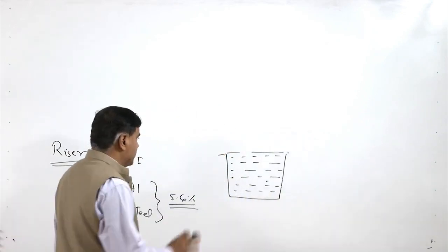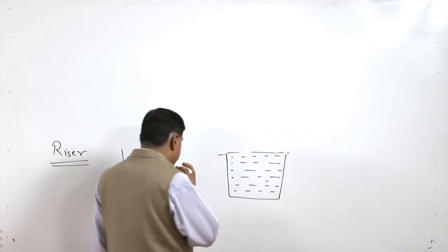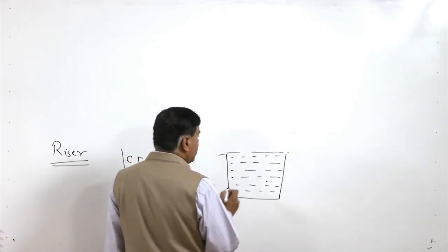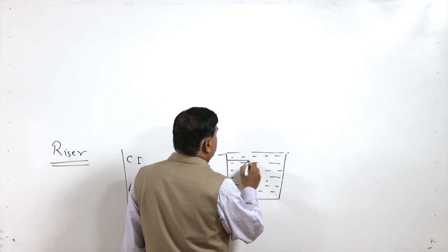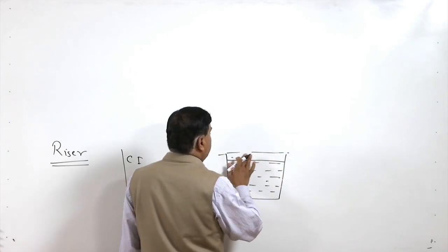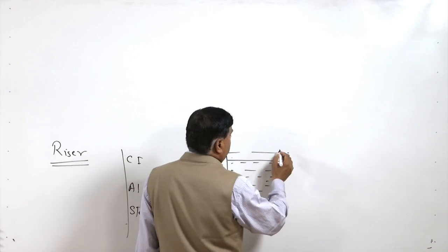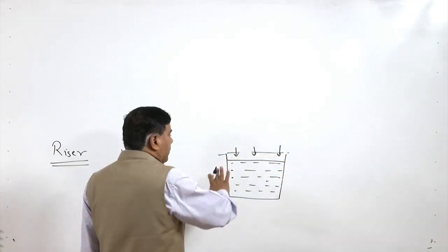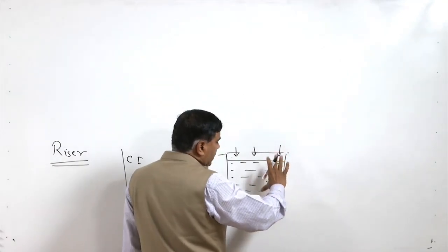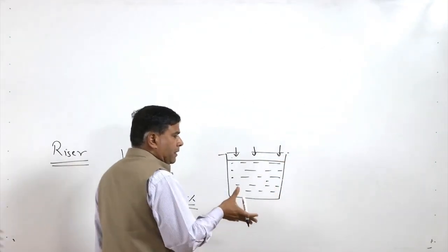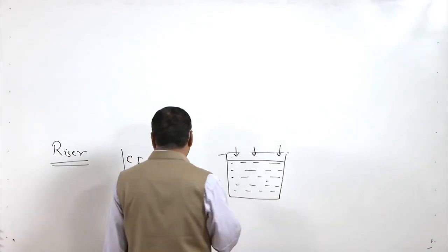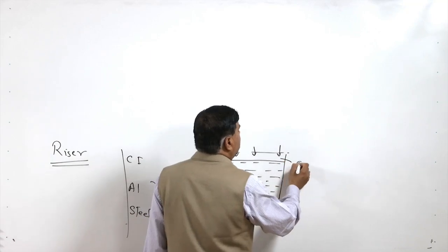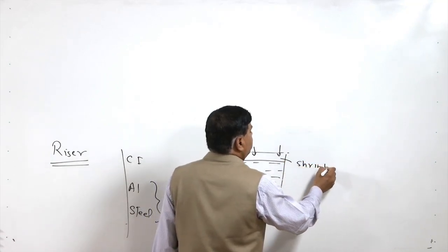There can be different conditions related to the solidification, but if 5 to 6% shrinkage is taking place, then we will end up with a lot of reduction in the volume, and we may find that at the top some of the space is still left to be filled in, because the molten metal solidifies with a significant reduction in the volume through volumetric contraction, and this will lead to the shrinkage